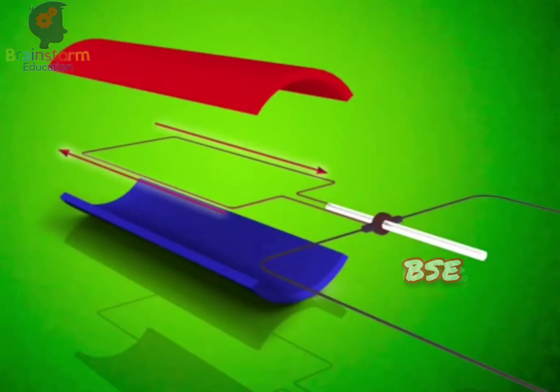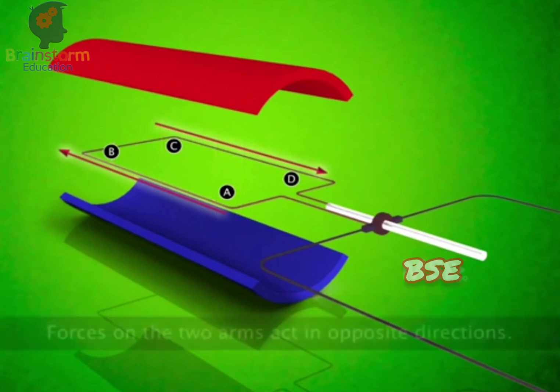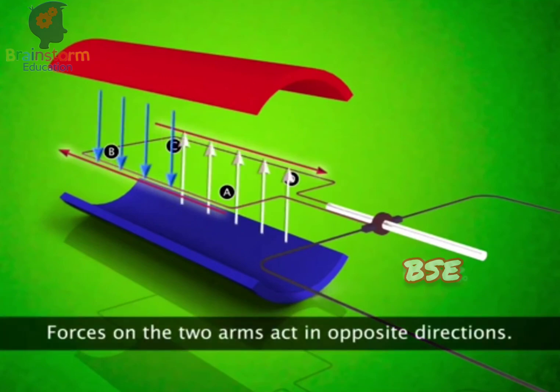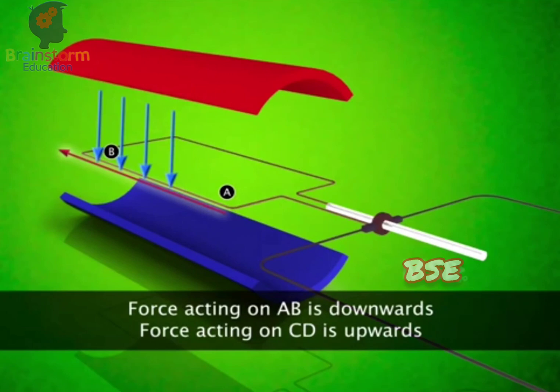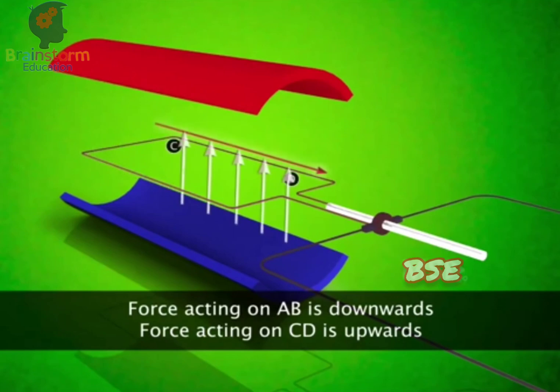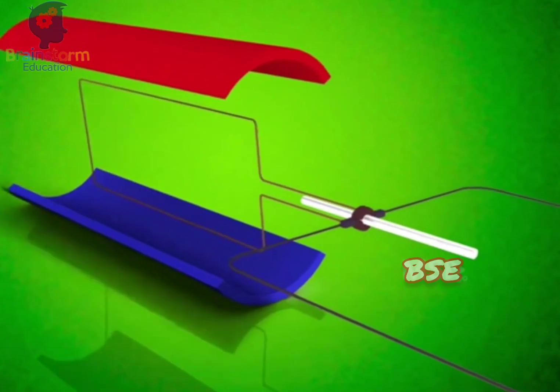When a current passes through the coil ABCD, the two arms AB and CD are perpendicular to the direction of the magnetic field. The forces on these two arms act in opposite directions. The current flows from A to B, so the force acting on AB is downwards, and then from C to D, so the force acting on CD is upwards. Now the coil and the axle rotate anti-clockwise.